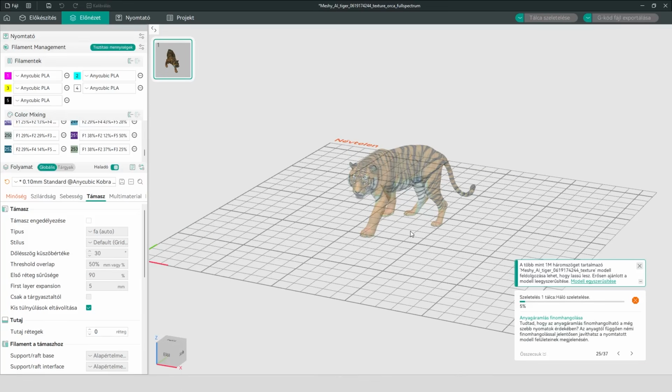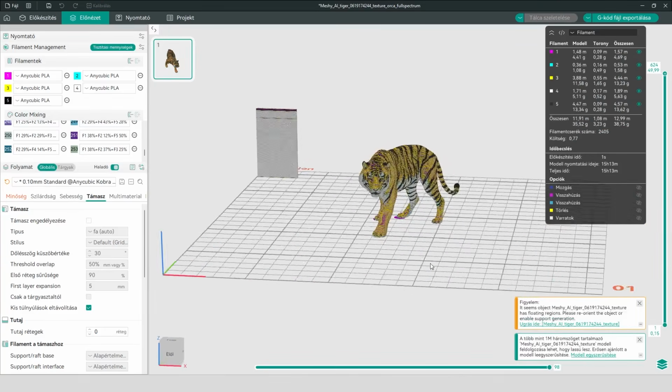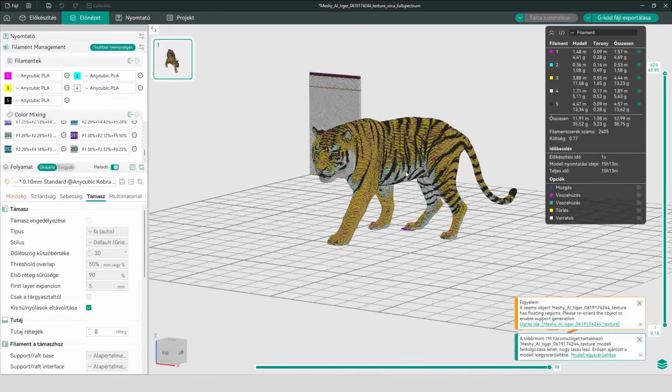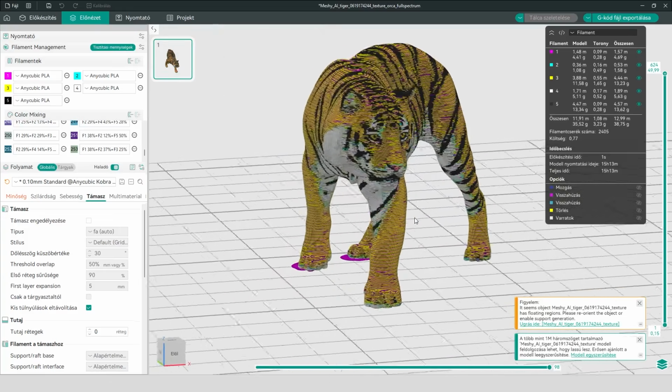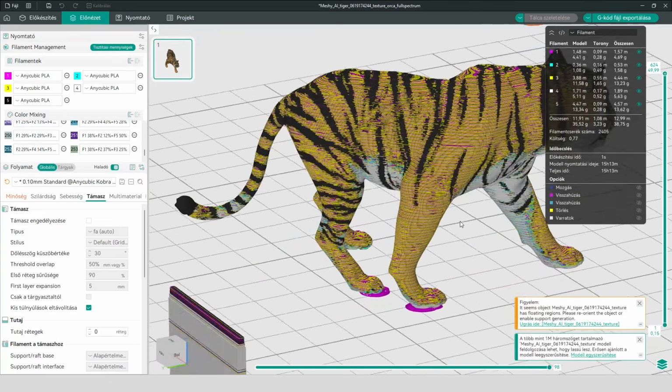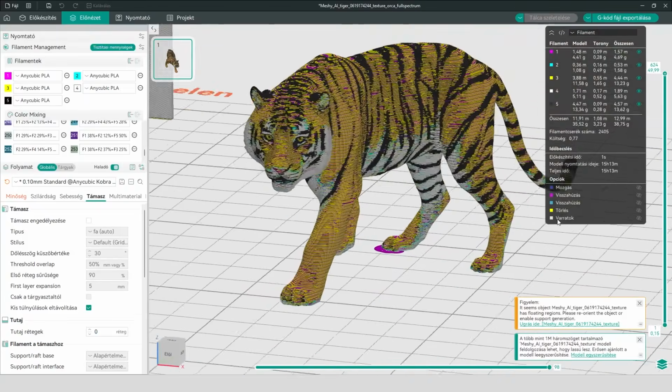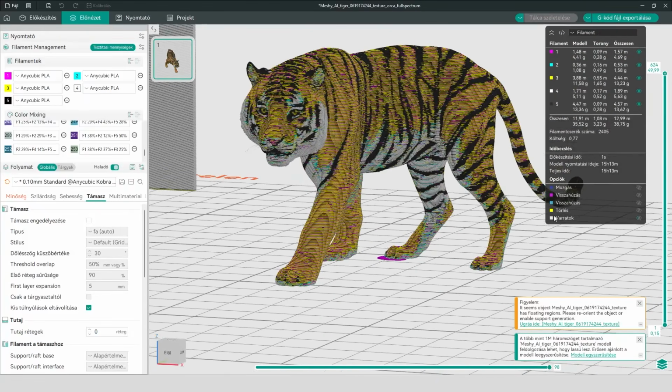Tips and common mistakes. There are a few important things worth keeping in mind. The final printed colors match the colors shown on the loaded model itself, not the colors shown in the already sliced preview image. The shade you see in the slicer's preview can differ from the color of the actual printed model. It's worth keeping this in mind and fine-tuning your color settings if needed.